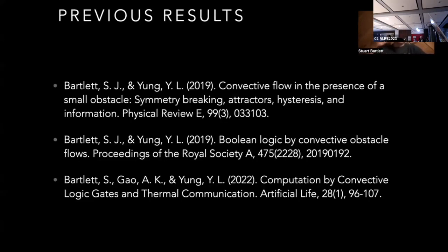And what we found is, due to what's known as the Coanda effect, convection plumes actually align themselves with obstacles due to the asymmetry of moving one way or another. And it turns out that you can configure those convective systems with multiple momentum sinks, and they will show bistability or multi-stability, and even a memory of their past states. You can actually get them to exhibit hysteresis loops.